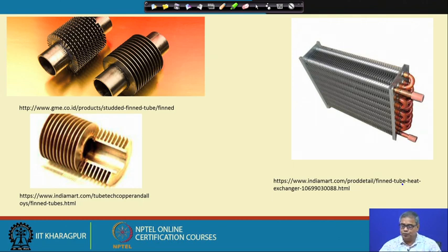which is outside the tube, and to enhance the heat transfer with the gaseous fluid outside the tube, we will have fin. So, you can see the fin, and these are kind of integral fin. So, one fin plate is pierced by a number of tubes. So, this is what I have mentioned. In this case we are seeing individual fins, in this case we are having one fin with a number of tubes piercing it, that is a fin plate.